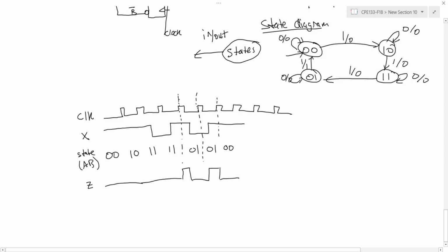Okay, so this is the timing diagram for the sequential circuit, but what does this mean? What is the sequential circuit doing? Well, this is a little bit trickier, but let's try to analyze what's going on here. So my input, I read it on the clock pulses, the sequence 1, 1, 0, 1, 0, 1, 1. And the output was 0 until I had this transition on the 6th clock cycle.